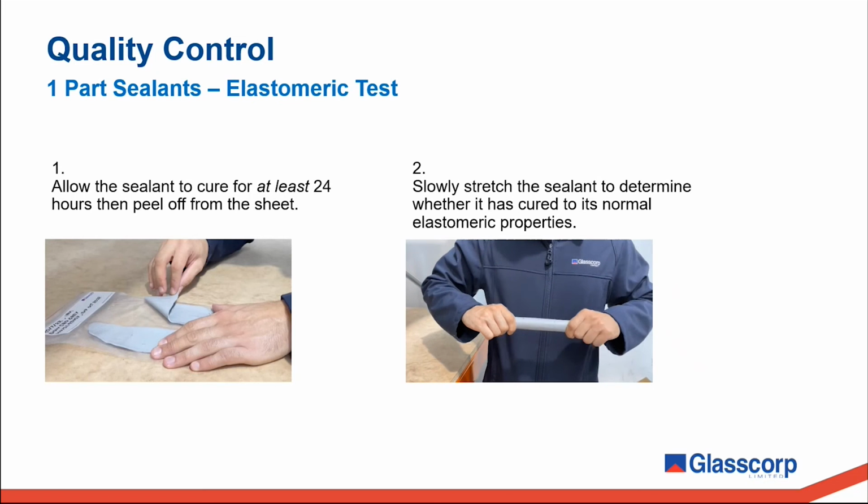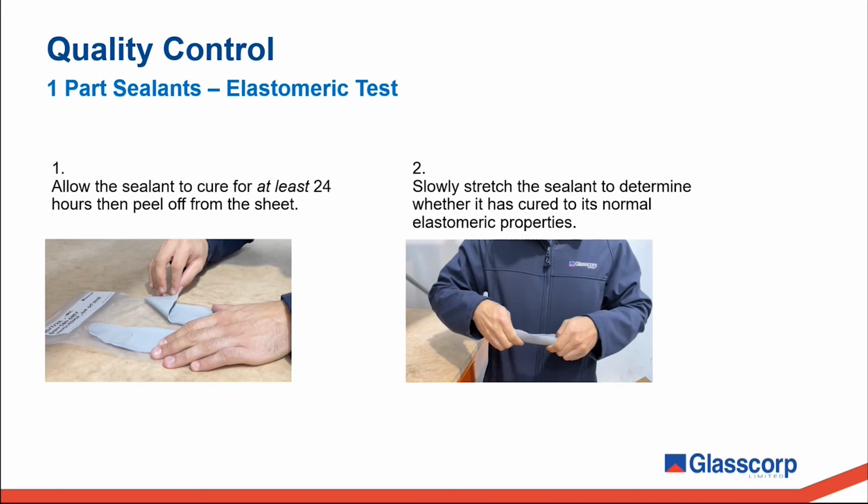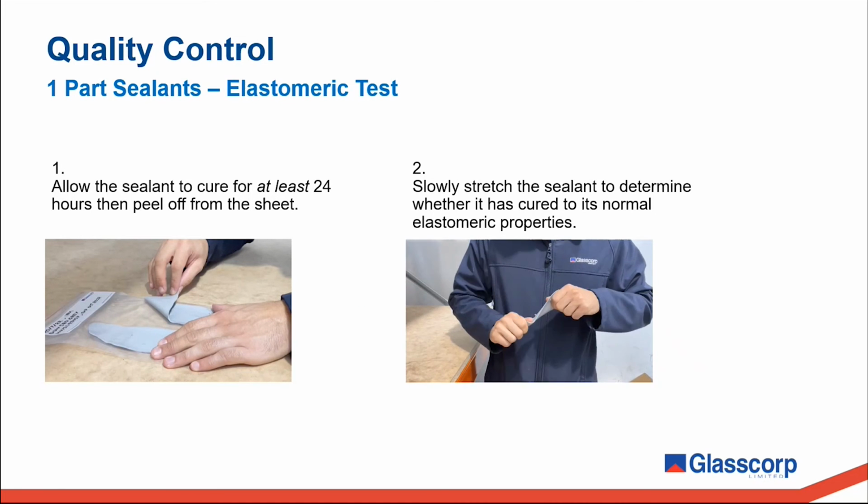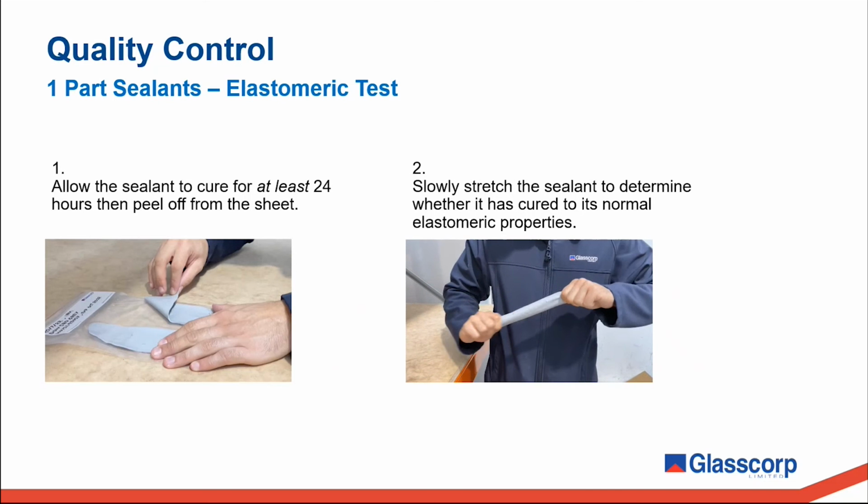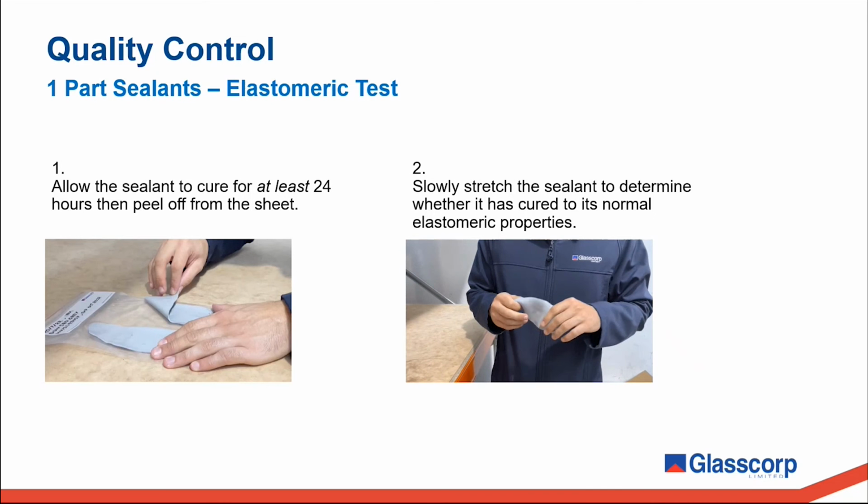Slowly stretch it to determine whether it has cured to its normal elastomeric properties. If the sealant is not cured properly, or if you see irregularities, such as the sealant being very stretchy or very brittle, don't use the material and let us know.